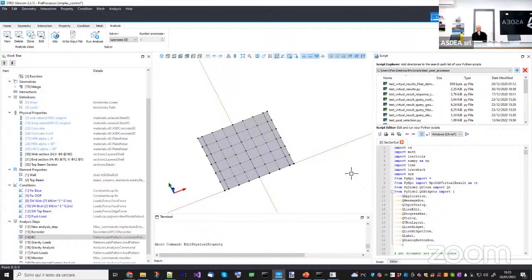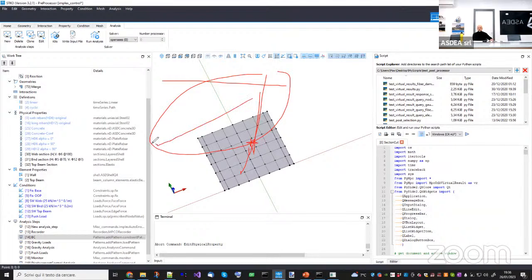Actually, it is taken into account in two different ways. One is because the compression field approaches and all those things were used in non-tensorial models, so they didn't have the concept of the surface. When you have a yield surface like this, you're already doing that. For example, if I am in uniaxial compression, I have this strength. If I am in biaxial compression, it increases. If I am in compression-tension, it decreases a lot. So there is already an interaction like that.